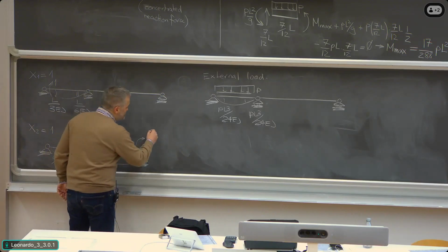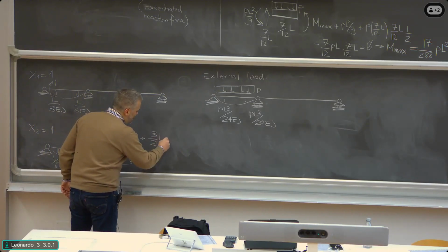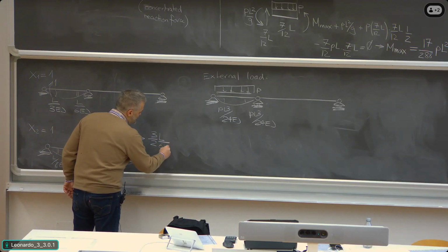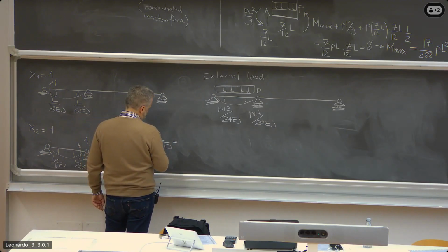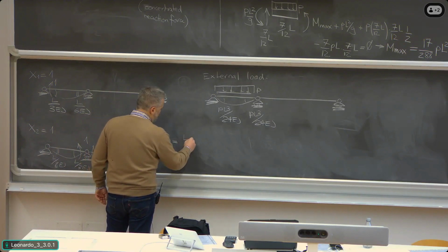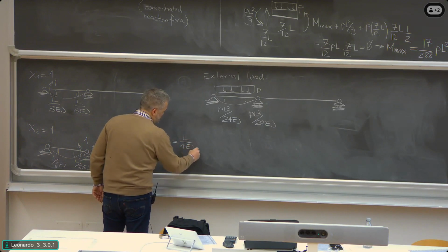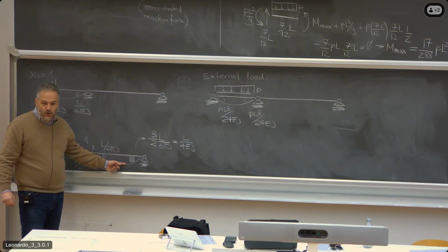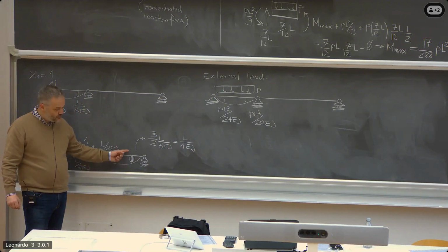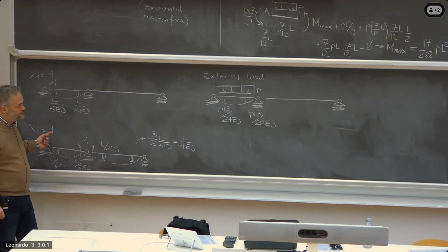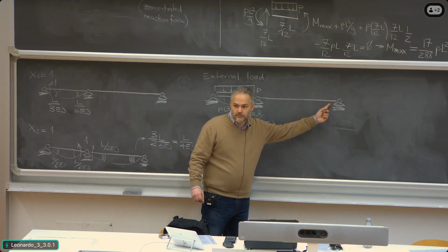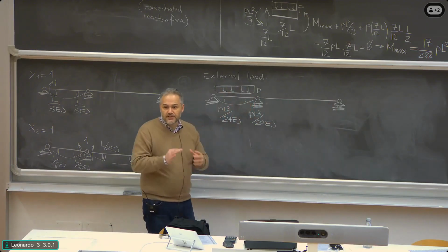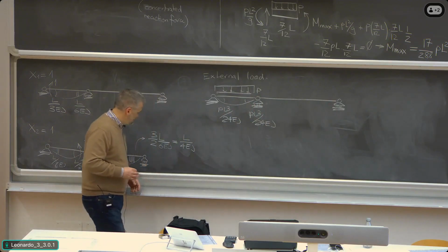So putting this all together, this will be 3 divided by 2L divided by 6EJ equal to 3 divided by 6 is 1 over 2, L divided by 4EJ. Counterclockwise. As you see, it's counterclockwise, for x2 equal to 1. What is the rotation caused by the external load? Look here, 0. Summing this all together, I now choose the sign.